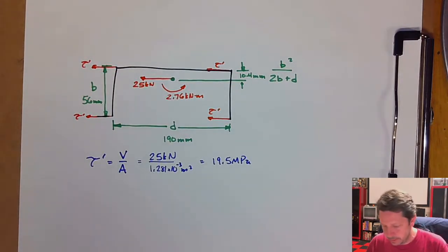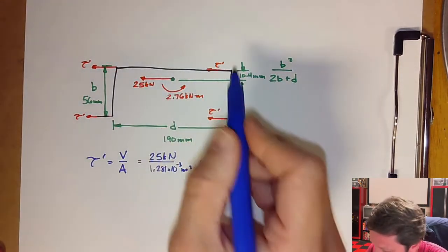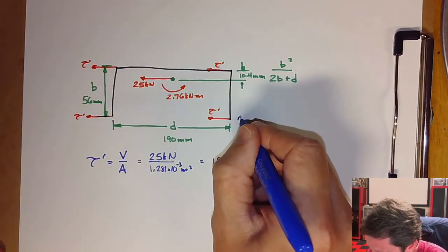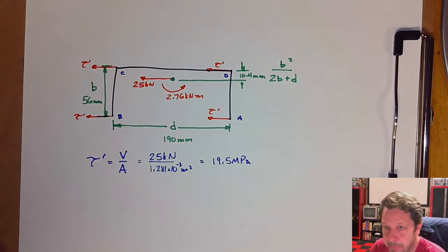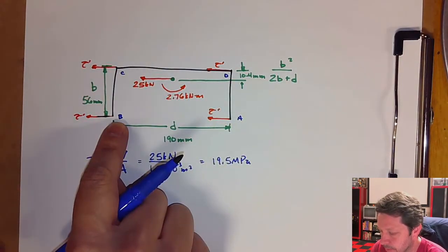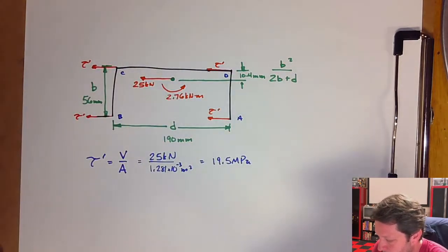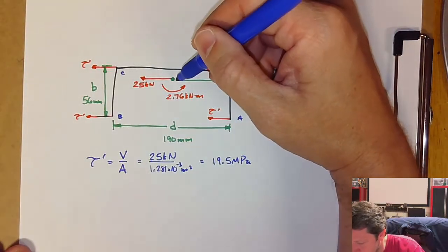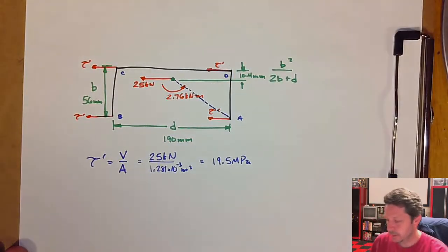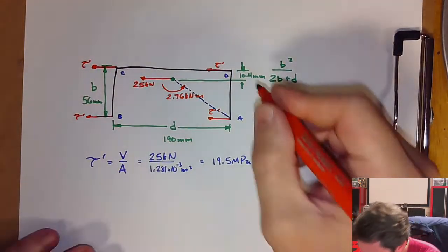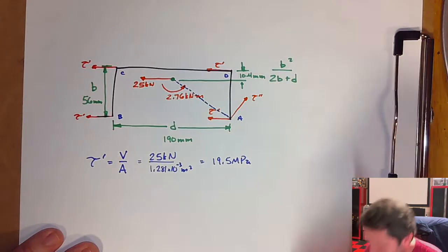The moment arms that they dealt with now are, you go to the centroid of the weld group, and every point of interest, so we did point A, B, C, and D. Those are the points of interest for us. A and B are going to be similar as far as the stress, and C and D are going to be similar as far as the stress goes. But let's look at A. So the moment arm that they're going to calculate is basically this thing right here. And the secondary shear stress is going to be perpendicular like this. And we need to calculate that.